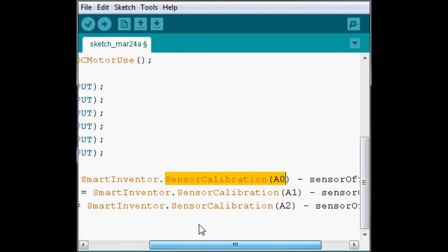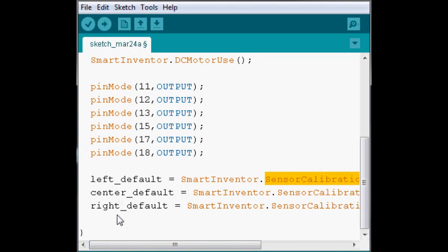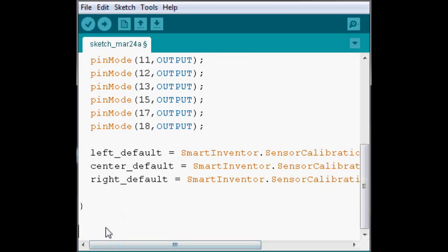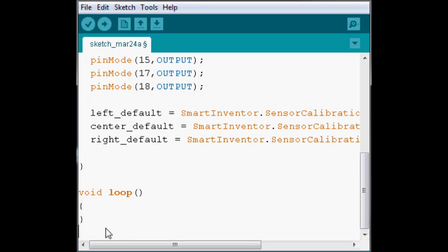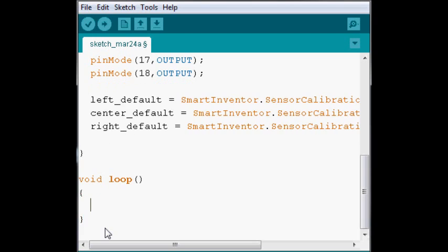This is going to allow us to make sure that when we put our finger there, we definitely will see a difference from what it usually sees. If we hard code our statements later on to have a number that we're looking for, we run the risk of not getting that number because the sensitivity of our sensors is different than what we expected. So doing this in the beginning will allow us to run our robot in different circumstances and almost always get a result.